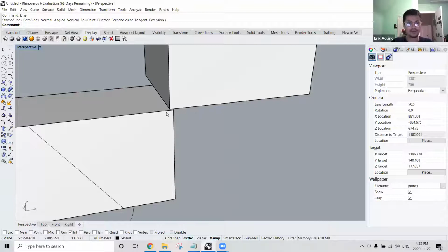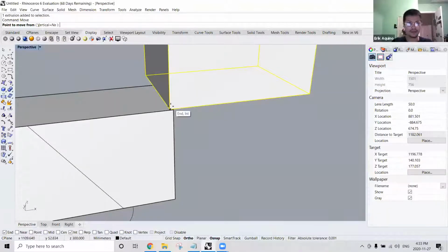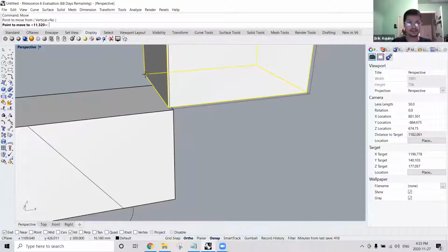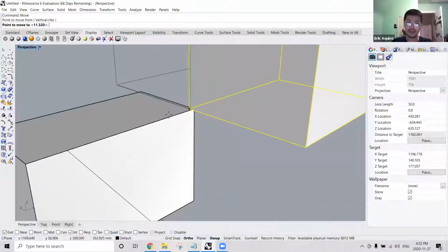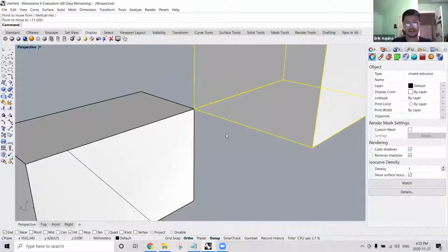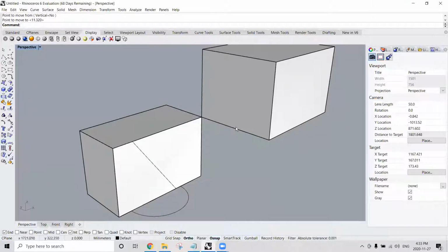And how I put the corners together is I use the end O snap, and check that, and when I typed in my move command, I selected one of the corners of our box. We'll select this and simply hover over another corner, and that should lock to this corner of the box. Is that working out for you? Yeah. Thank you. Yeah, everything great.